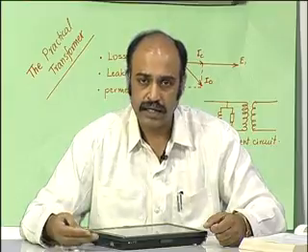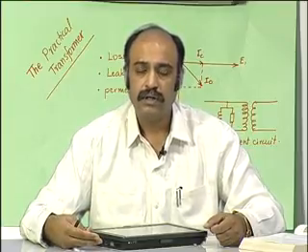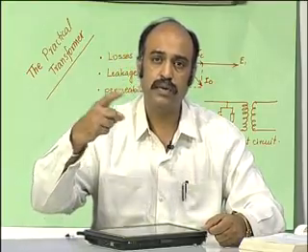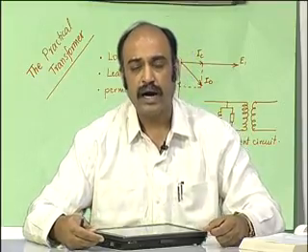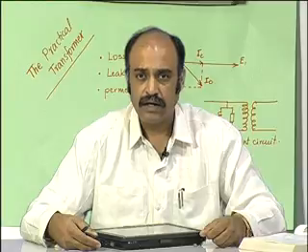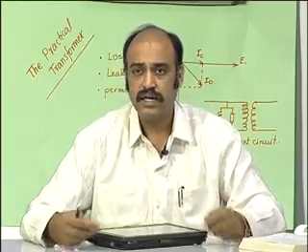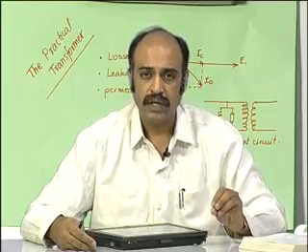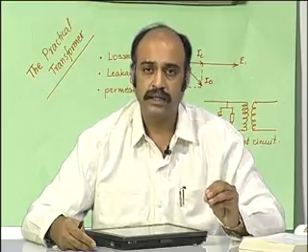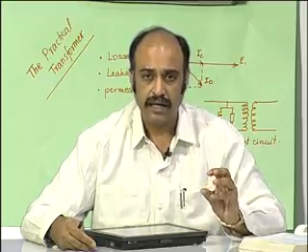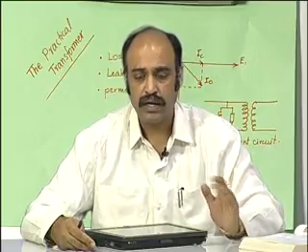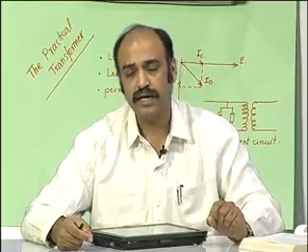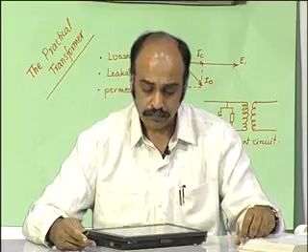Because whether it is the reactive load or the active load, the transformer has to undergo so many cycles, which means so many traversals of the hysteresis loop, and also the eddy currents in the transformer do not distinguish between the reactive load and the active load. Therefore, the heating in the transformer is related to the VA or the apparent power that is flowing through the transformer, and therefore, the nameplates of the transformers are rated in terms of VA rather than watts. So, this is one issue.